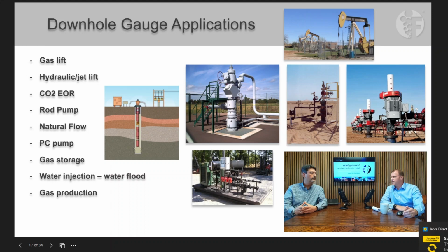Well, when we put a gas lift system on, we have tubing pressure, casing pressure, and injection rate. And so we lose that downhole visibility. And in my opinion, that's been a big application, is actually seeing what your flow and bottom hole pressures and temperatures are when you have a gas lift system.